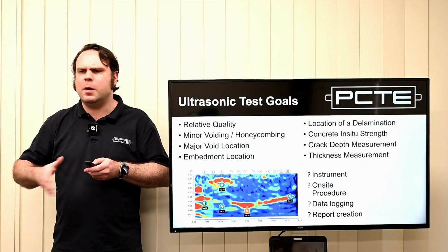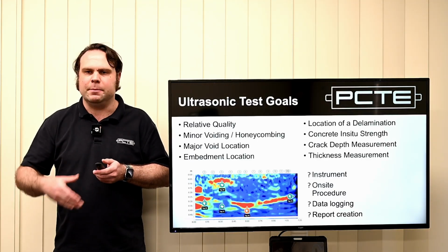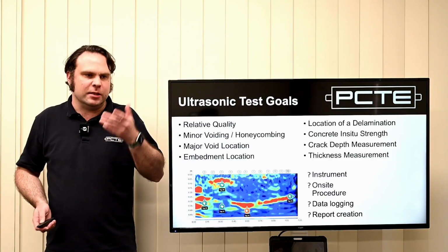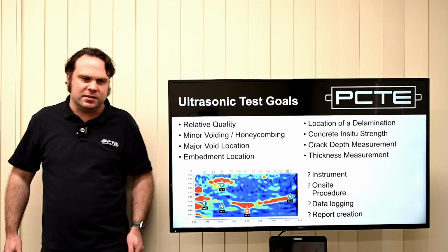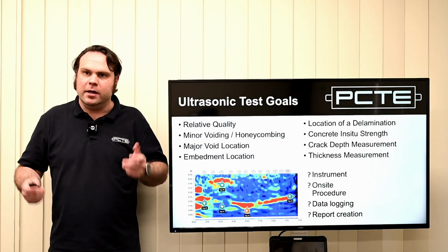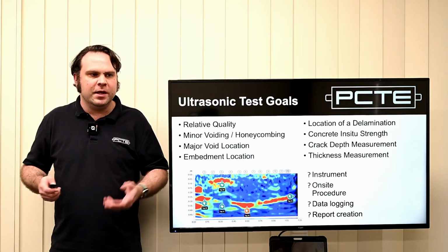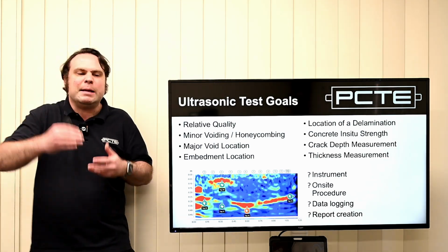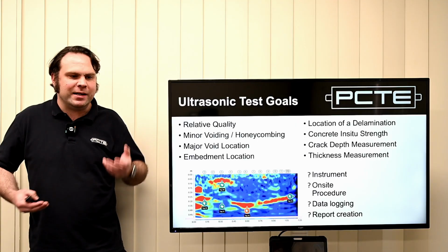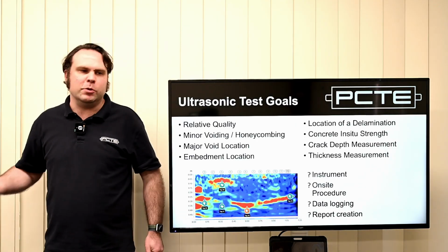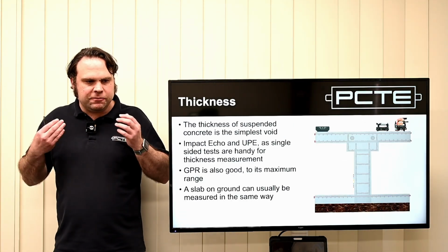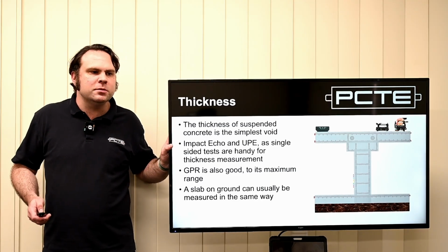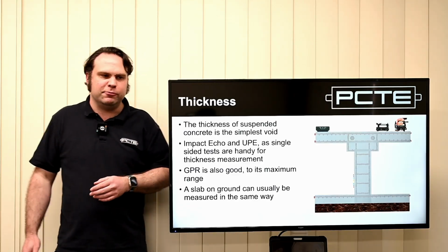What sort of data logging function? You'll find with all of these tools, you're probably going to be setting up grids or setting up some way to take more than a single measurement, because it's pretty meaningless by itself. You want to compare a larger data set, so be mindful of grid setups and learning the data logging of your devices, because all of them look simple to use, but you'll find if you haven't practiced before you go out on site, you'll make mistakes, you'll need to redo the work 2 or 3 times. A bit of practice ahead helps, and just be aware, what do you want to show the client at the end? So the final portion of this presentation, I'm going to show some different problems and just point out which devices are going to be appropriate in each case.